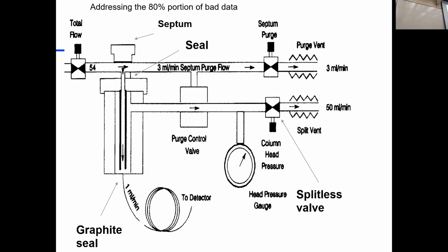On some occasions, we have a problem out on this end. Maybe this valve hasn't been looked after, maybe it's been abused, so we cranked it too tightly. And so we can mess up our outlet flow by not having the right restriction here. So kind of one, two, three, four places primarily that we look for leaks. We look for problems in gas flow.